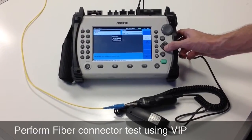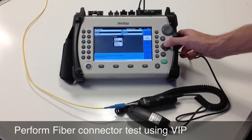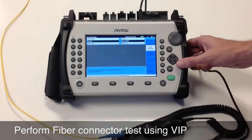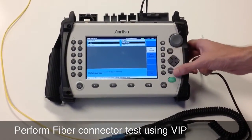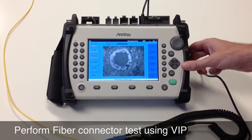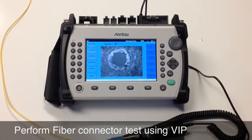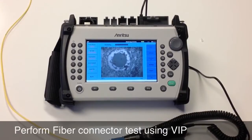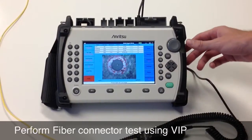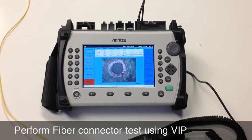Before initializing the test, make sure that your probe model and probe tip are selected correctly in the test settings. Use the green Start button to initialize the automatic analysis capture. It will determine whether the connector is passing or failing, and then you could bring up the analysis report to see exactly what areas are failing.